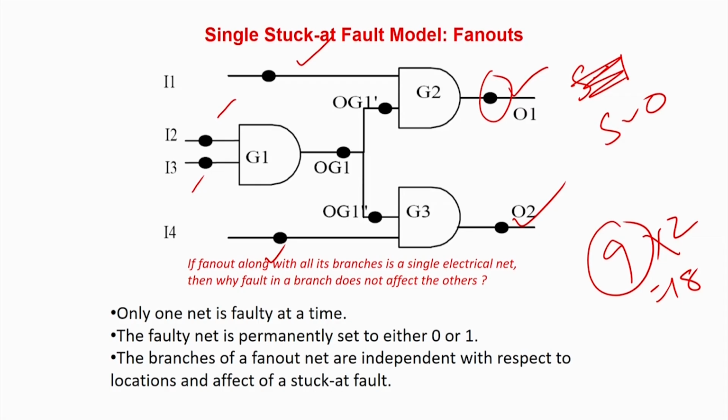One byproduct that has been found for the fault model is that if there are n lines, of course there are 2n faults, 2 into n, because stuck-at 0 and stuck-at 1. But 2n patterns are not required. The patterns are much lower than that, because one pattern can test multiple faults. So in this case we will not require 18, we will require much less than that.